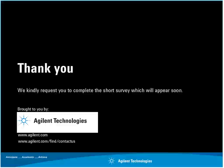All right. To measure a signal with a rise time in the nanosecond range, we have a few solutions. One of them is the Agilent 8990 series peak power analyzer, which is the Agilent power measurement equipment with the best rise time performance of 5 nanoseconds.